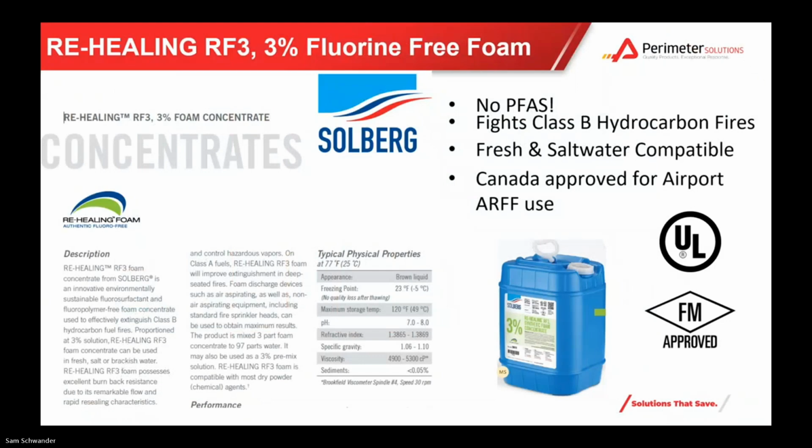So I'm going to go into two products here, and Pat and Sam have mentioned both of them. First, the Rehealing RF3. This is a hydrocarbon fuel only product. This is FM approved, UL listed. This was the original fluorine-free foam that worked through a non-aspirated sprinkler, and it set the bar for what could be done with fluorine-free foam technology. It works in fresh and salt water, and it contains no intentionally added PFAS. This was a really big product for us and I think we launched it around 8 years ago. So there have been fluorine-free options for sprinkler applications for about that long.